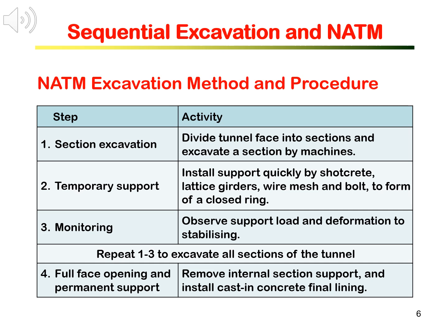Second, the excavated section is temporarily supported, usually by installing quickly the support elements such as shotcrete, lattice girders, wire mesh, and bolts to form a closed ring. Using shotcrete as a quick support and form a closed support ring are key features of NATM and were highlighted by its inventor, Professor Rabcewicz.